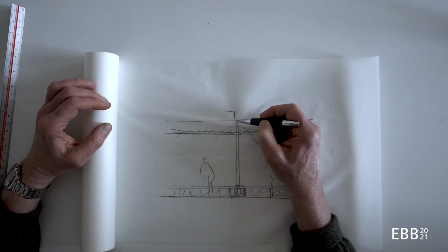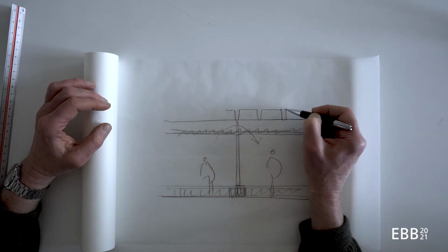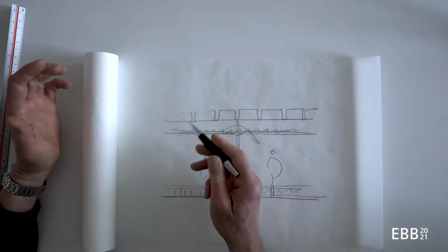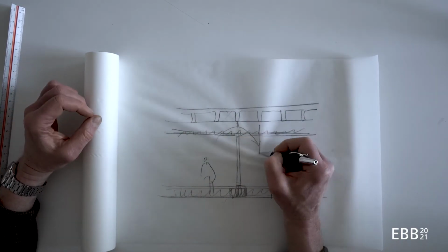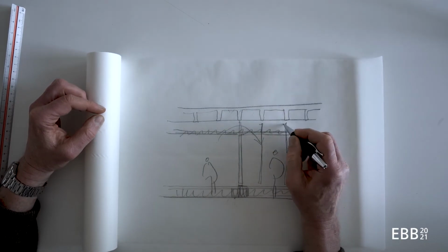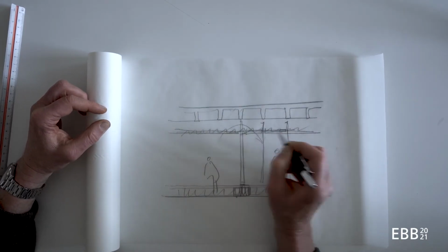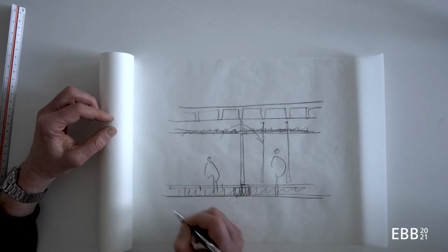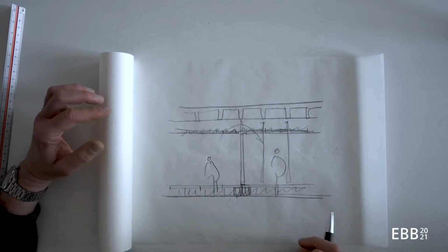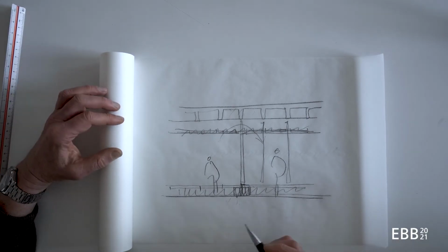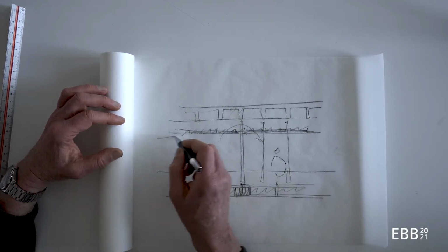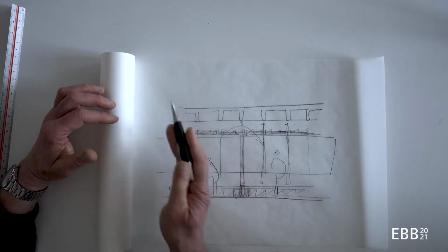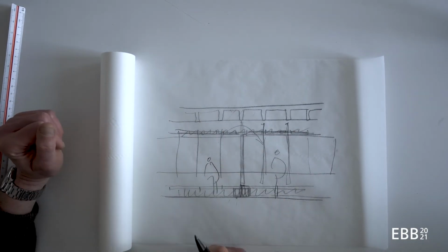It might also need a particular load-bearing system where you are foreseeing the positions of the non-load-bearing wall, and this might reflect on the suspended ceiling as well, to correspond to the possibilities to put the separating walls. And the whole thing will reflect in the facade as well, because at each mullion you could have a separating wall meeting the facade.